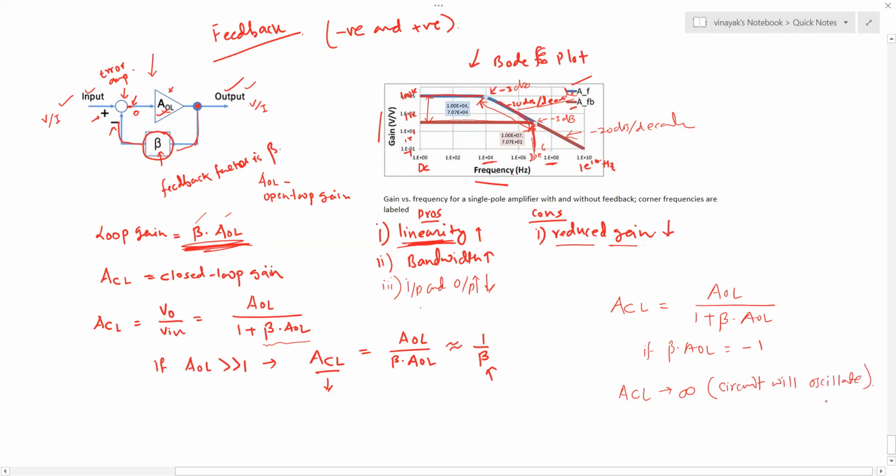Okay, so there is like Nyquist plot, Barkhausen criteria for oscillation, where we say that the magnitude of beta times loop gain is greater than or equal to 1 in order to achieve the oscillation. That is one of the stability criteria or oscillation criteria, in fact. And the stability criteria is that beta times AOL must not be equal to -1 for the amplifier to be stable.